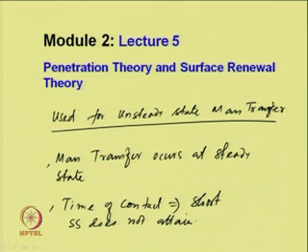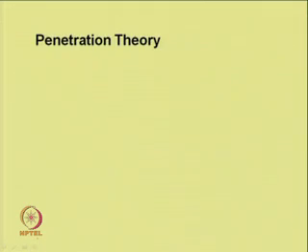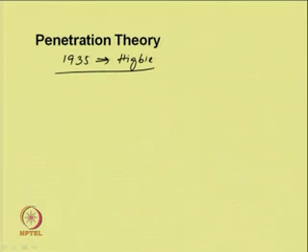So in this case we have to use a more realistic theory which assumes unsteady state condition for mass transfer in turbulent conditions. One such theory is penetration theory, and in 1935 Higbie assumed a pool of liquid in which a bubble is rising.